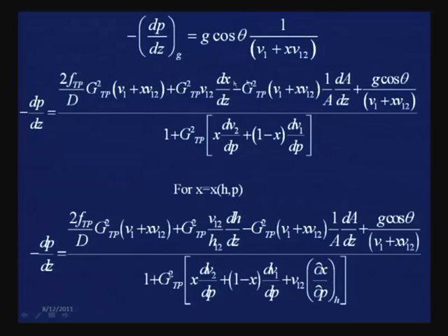And other than FTP, if you observe both the numerator and the denominator, you find that other terms which we have, the pipe diameter, the mass flux, even the quality change with length, can be obtained from enthalpy balance if at all there is a heat balance, otherwise this term cancels off. And the other thing, the phase physical properties, the taper, if there is a taper then we have this term, otherwise this term also cancels out. So, therefore, more or less you can obtain everything else from known input parameters. This we have done for this situation.